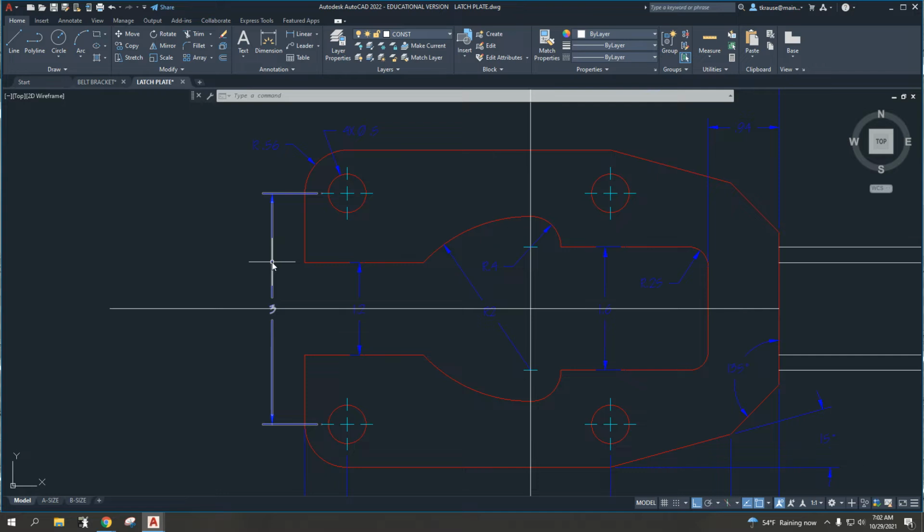So once you know the overall height of the object, you'll have a midpoint over here. You can project a line, and you'll take that 1.2 and divide it in half. You'll offset this line up to get this, offset this line down to get this. Same thing here. Offset this and take that 1.6, divide it in half, offset this line up, and so we'll have to work on some geometric construction.